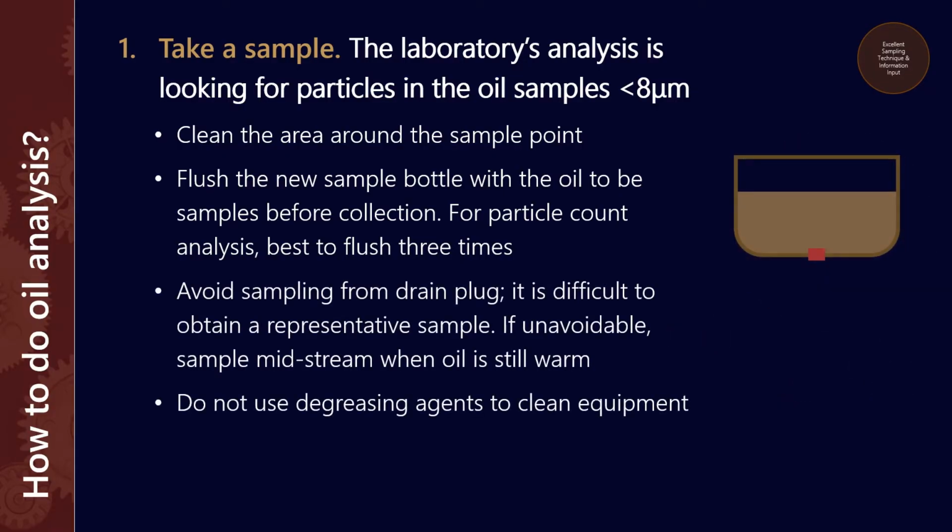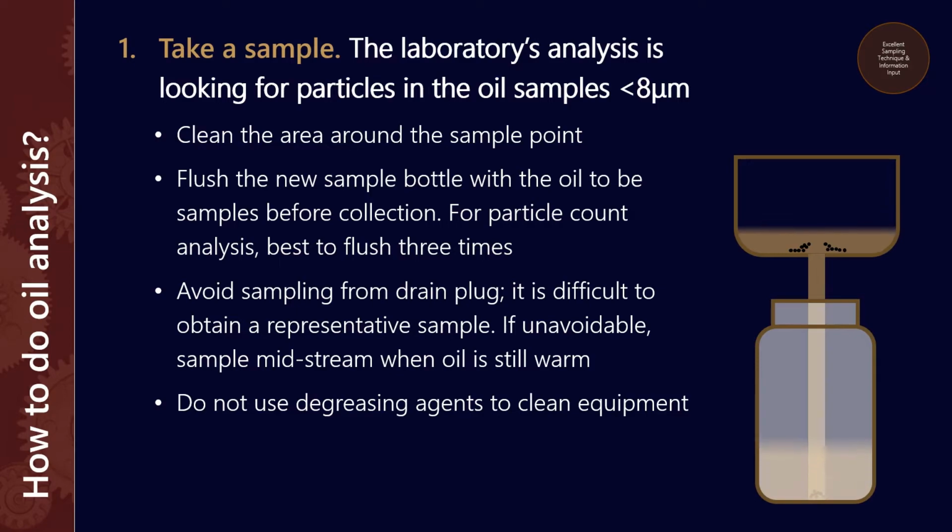If at all possible, we want to avoid sampling from the drain plug. Now, the reason for this is because the sump is a low flow area and it's probably the coldest part of your equipment. And so all of the used additive, contaminants, machining swarf, all of that kind of stuff ends up at the bottom. So if you were to take a sample from there, all of that crud ends up in your sample bottle. Okay, and that's going to contaminate the sample and cause the results to not be representative.